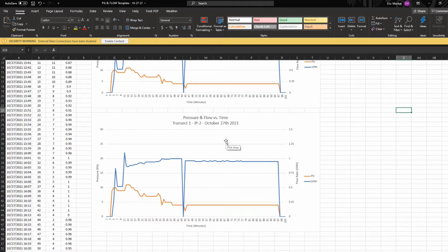We're pretty shallow here. We're under 10 feet below grade, and our target was 1 GPM flow rate, low flow, due to the shallow nature of the injections to try to avoid daylighting. So this is very low on this unit's capability. We have the capability of going up to 10 GPM per leg, all 10 legs running at the same time, for a total of 100 GPM going into the ground.